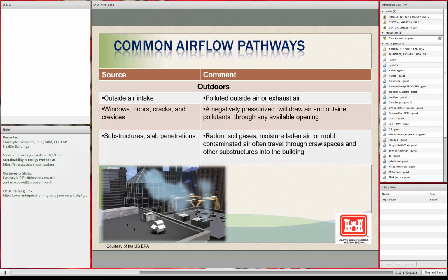But also, indoor air quality revolves around radon. It's a hot button issue, especially in the mid-Atlantic. You get into the Blue Ridge and up into New York and New Jersey, for example, where they do have some radon issues occasionally in the ground. Maintaining and monitoring that can prevent a lot of things. If you have crawl spaces, if you have substructures within a building, knowing that radon's an issue, and if you do have an issue from it, manage it. Have a radon mitigation system, etc.